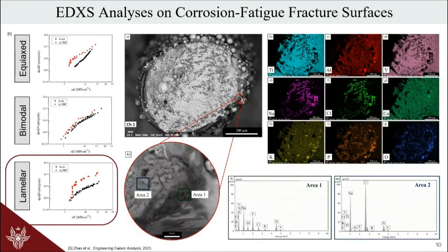However, we wanted to go a step further and also investigate the different chemical ions in the composition on the overall surface of our failed specimens. What we could see is that we confirmed the presence of NaCl, but we also saw an increased content of oxygen, phosphorus, potassium, and aluminum, which might lead to the idea that the initiation has also been altered, with a local breakage of the passive TiO2 film and the formation of potentially corrosive oxides.